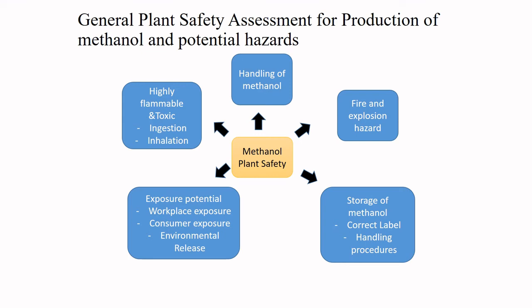Storage of methanol. When storing methanol, we must store it in a closed system or approved container which can be used to store the methanol. We never leave the methanol in open air. We also make sure to label the container based on the regulation. Storage handling in place at all storage and transfer points is needed.